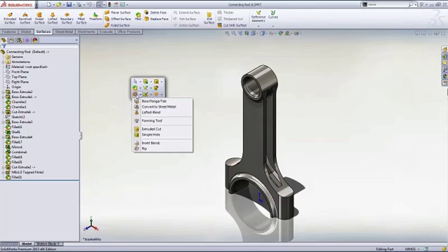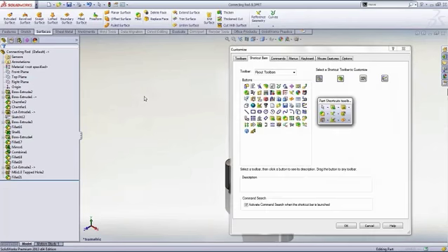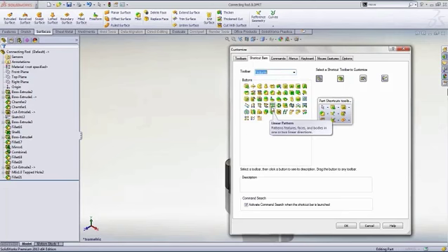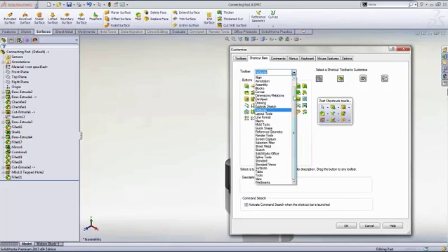With the shortcut bar up, just right mouse click and choose Customize. Now, I'm using SOLIDWORKS 2013 here, and this is a little easier in this version, but previous releases work fairly similar. Here, in this drop-down, you'll see that I have access to all the tools in the software. For instance, maybe I want to add some of these pattern tools from the features list. A better way to manage those might be using a flyout, and if we scroll back up to the top,